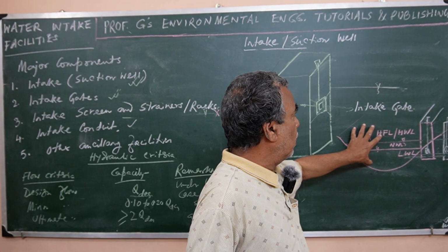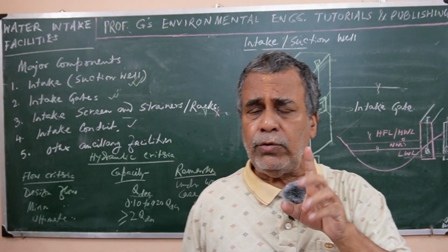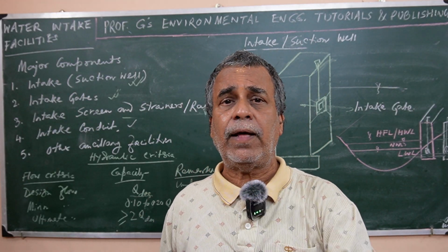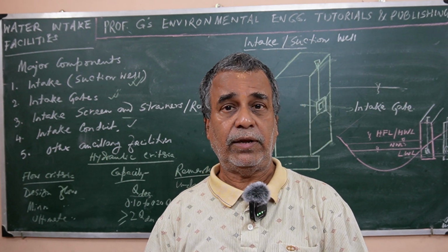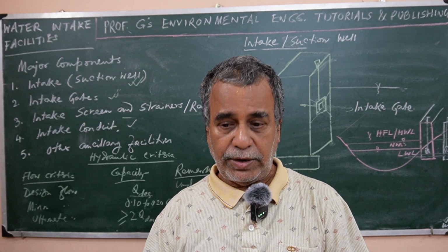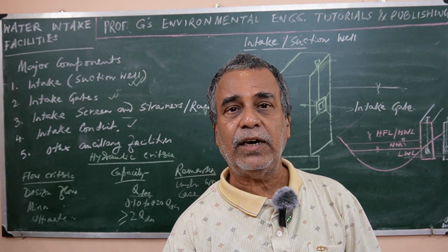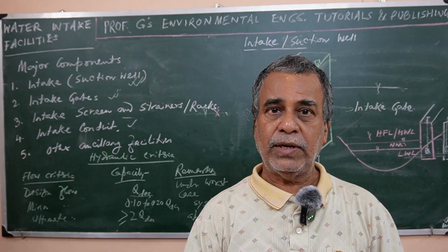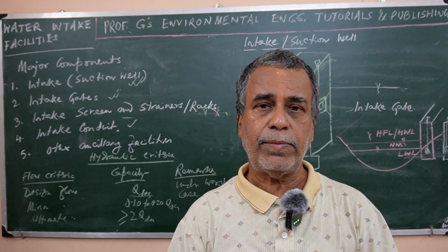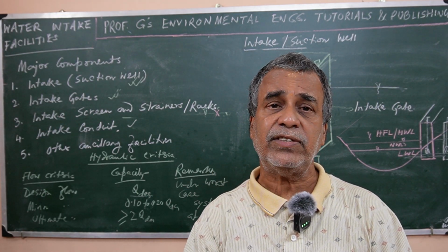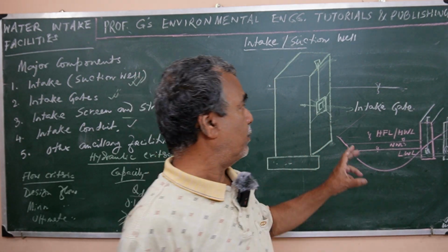So the first step is to find out the capacity of the intake well, the suction well, because that is important, since the water has to be held there, kept in the well for the supply. Supply may be continuous, may be intermittent also, depending on the requirements. Now, one or 2 days storage should be there. So sufficient storage capacity should be there.